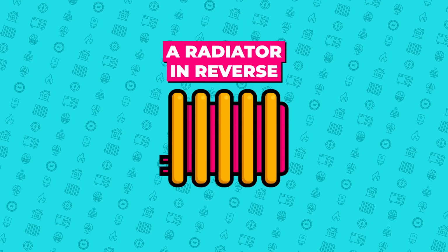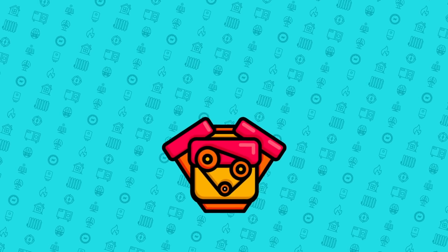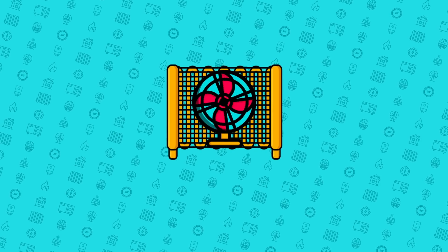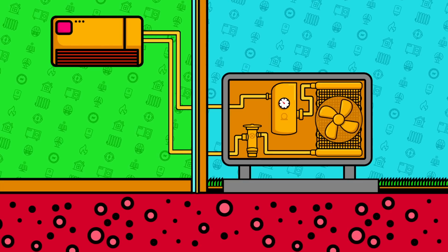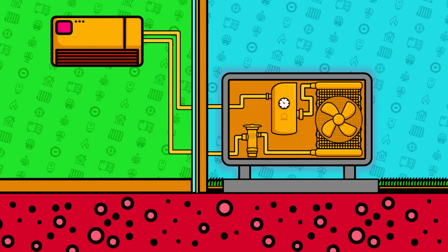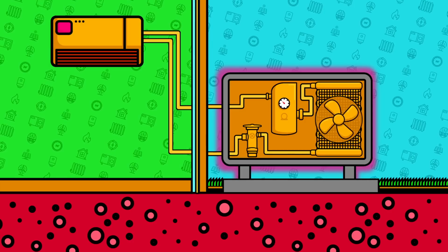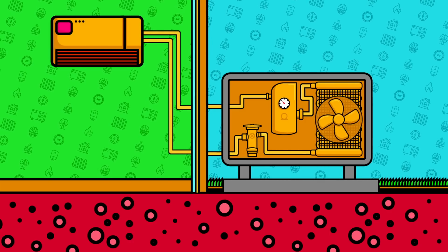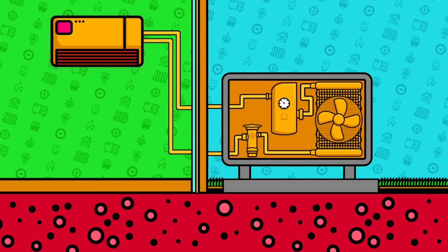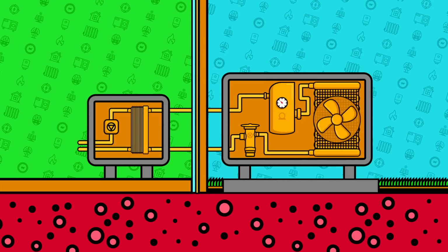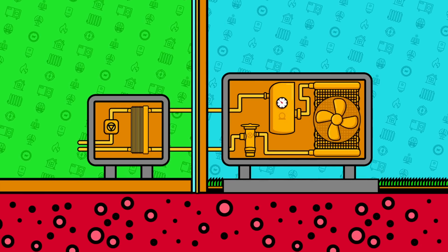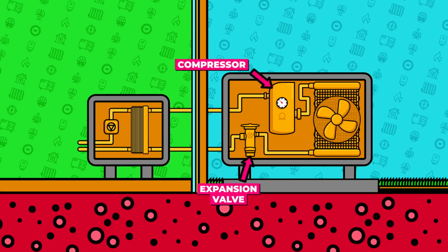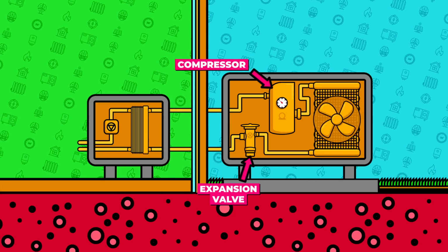To extract heat from the air, we essentially use a radiator, like a combustion car engine, with a fan blowing over it. These come as monoblock or split units. Split units were historically the most common. As the name suggests, these units are split into two. They have one outside with a condenser or evaporator, aka a fan coil, and another unit on the inside with a condenser/evaporator, fan coil, or a plate heat exchanger if they're going to power a water-based system like radiators or underfloor heating. The compressor and expansion valves are located on the outside units for noise and space.